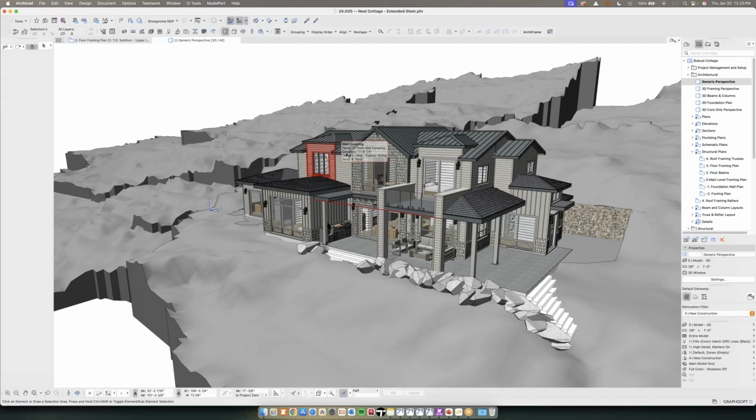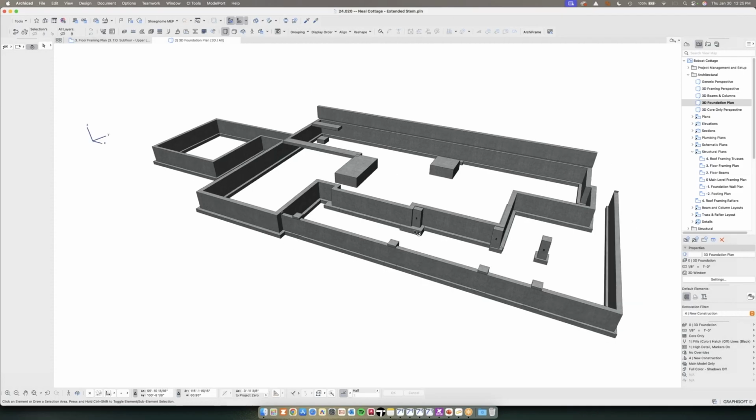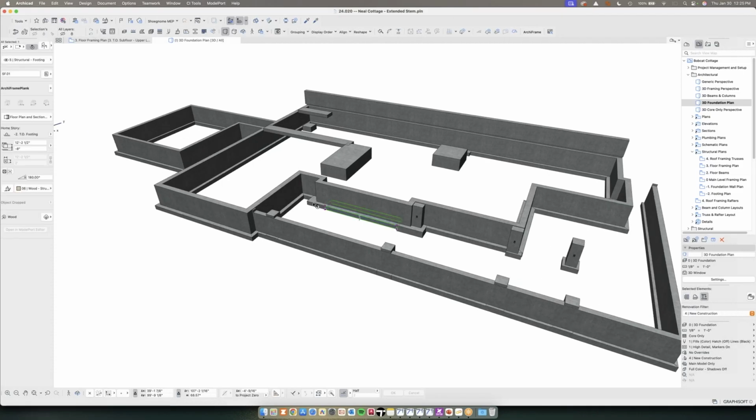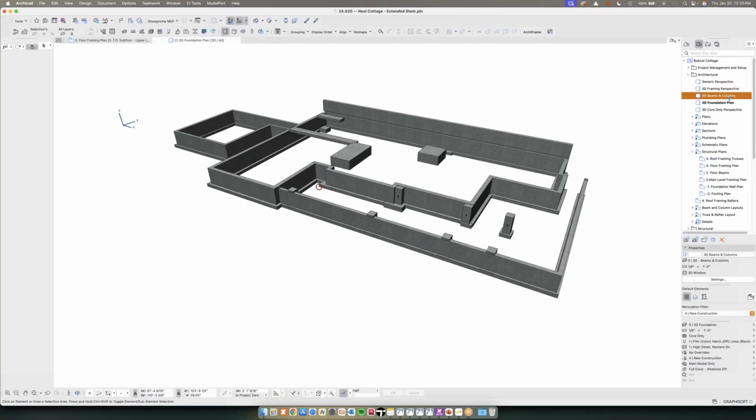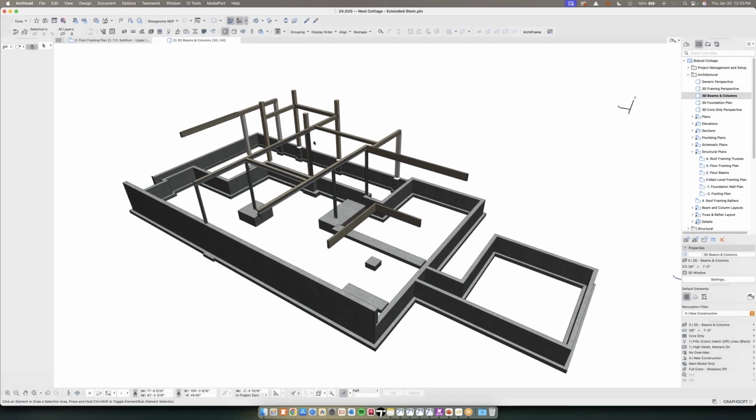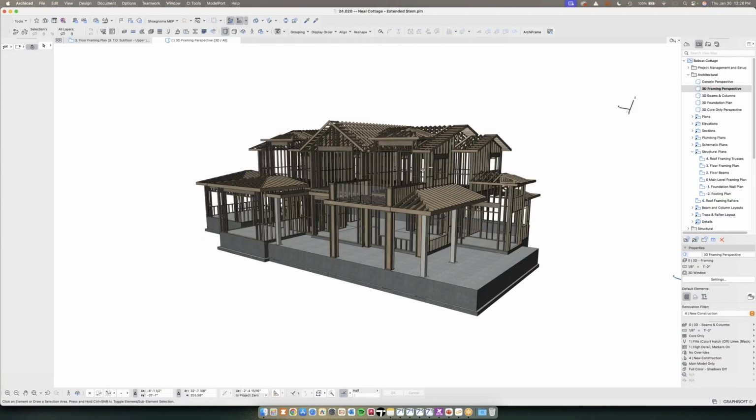But again, to drive down the individual elements and components, I've been able to separate these out for foundation plans. And all of my pad footings and strip footings, I've been able to convert to an ArchiFrame element, which allowed me to show them in the schedules as I showed before. But I'm able to highlight out the foundation plan, the beams and columns just as themselves to visualize where just the structural components are in this building, and then detail out in high detail the wall framing.